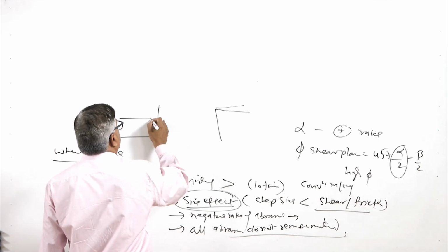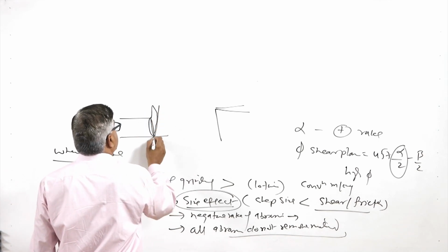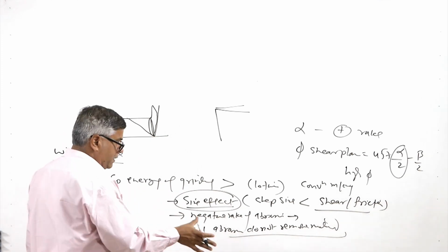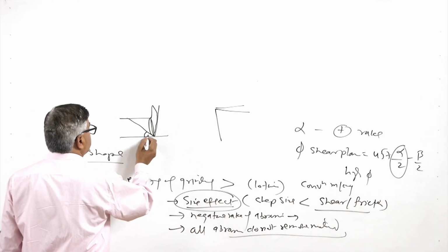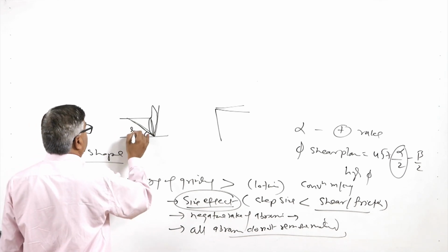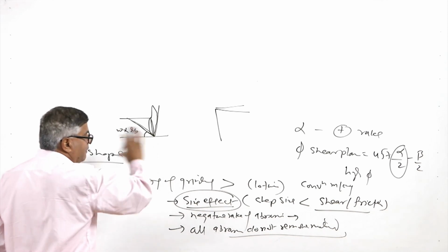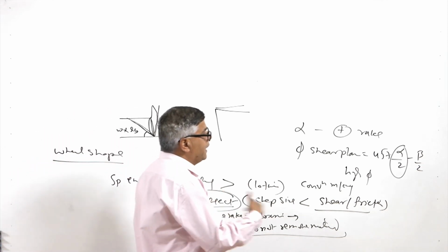smaller shear plane area. So, lesser forces will be required as compared to the case when a lower shear plane angle is used. This will be leading to the greater shear plane length, and the shear plane length multiplied by the width of cut will be deciding the shear area.